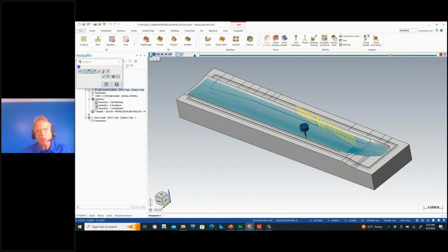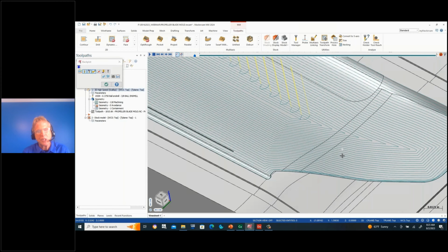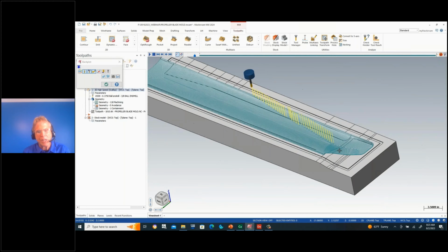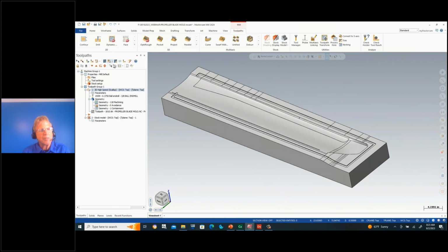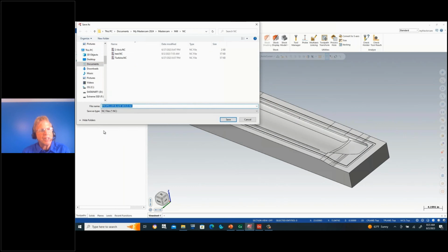And this is actually a roughing toolpath, although it takes the shape, so to speak, of a finishing toolpath. It's actually up above all 3 surfaces. But here we can see the clean, crisp 3-axis code, the entry points, the exit points. And as before, if we go out and we say, let's generate code,